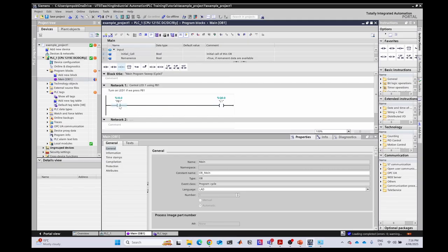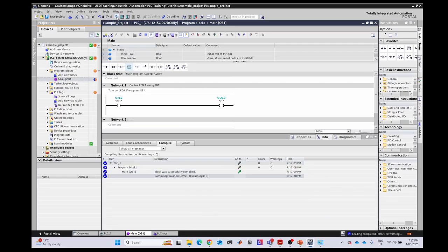So basically here we are saying that every time we push PV1, we make this value 1. This input is going to be 1 if we push the button. Then the signal, the voltage that is here in the power rail, will go through and will power on this digital output. It will change this memory, and this memory will change the output value at the end of the loop. Okay, so we can compile this and upload it to the PLC using these two buttons. This is for compiling, and this is for programming the PLC.